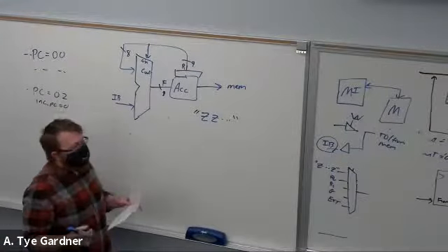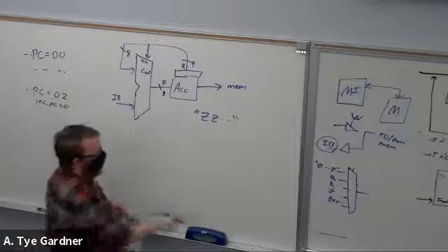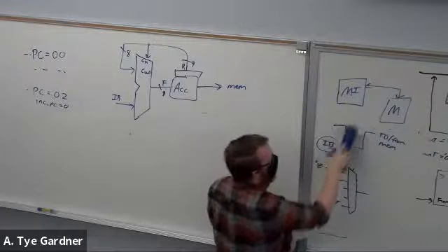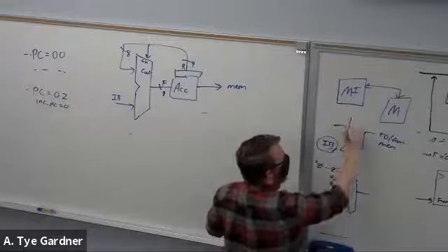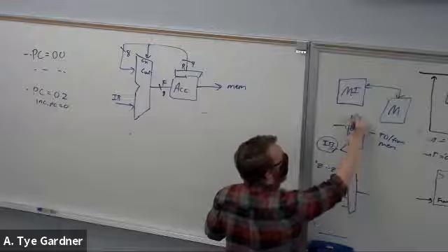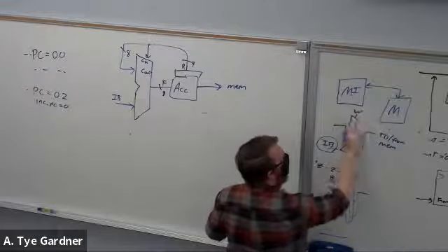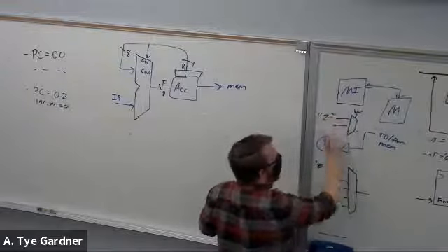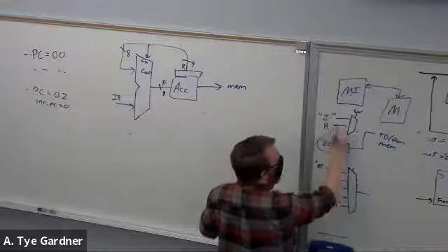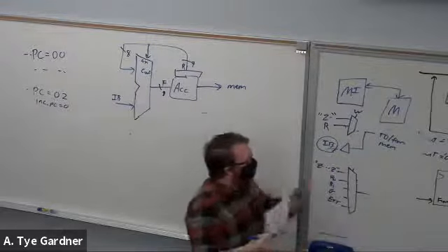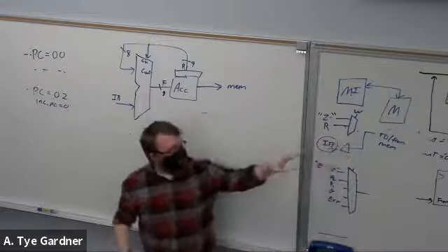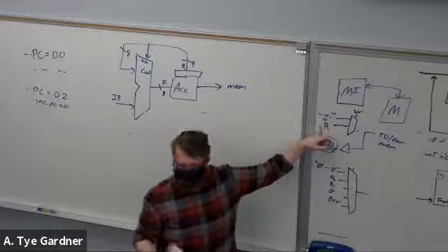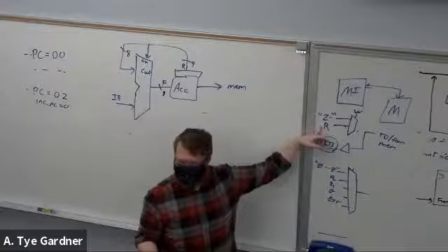And remember that when you design a new mux, right? So this mux here, I'll replace it. You don't have to go and make a new mux with port names of Z and R. You've already made several, I assume, 2 input muxes, right?